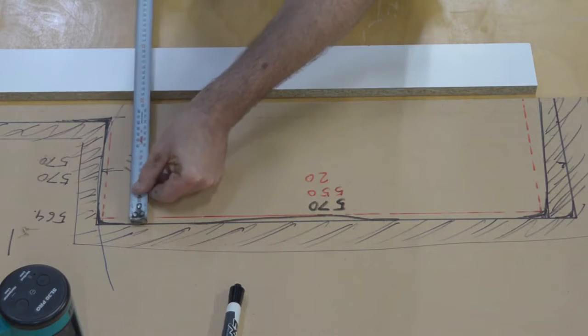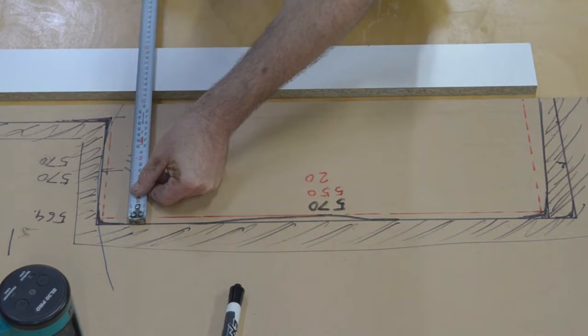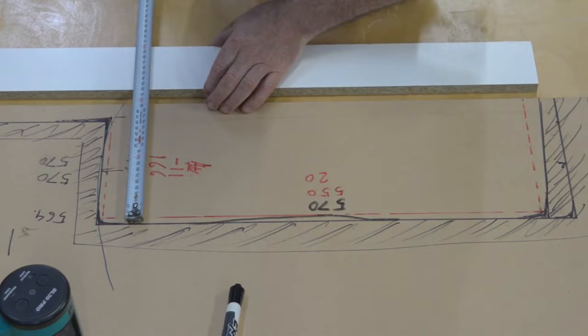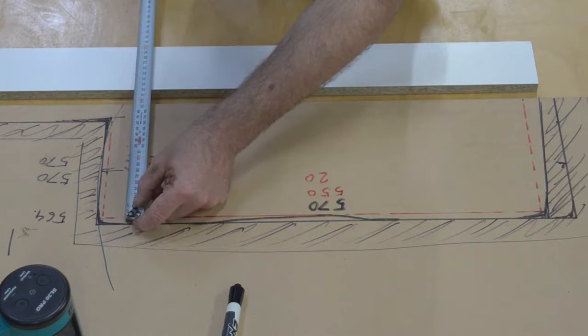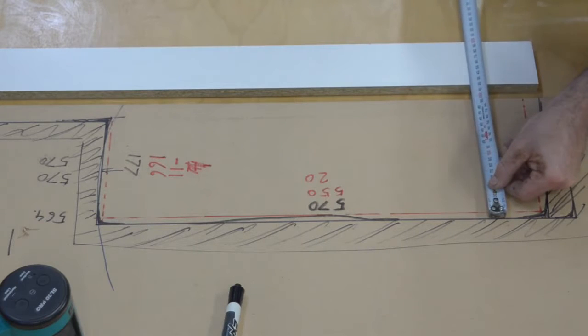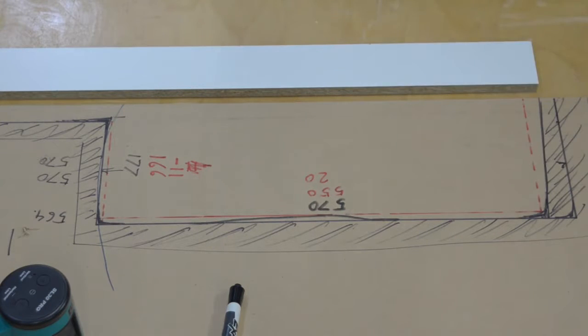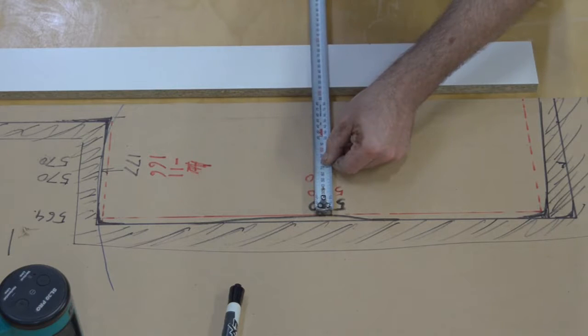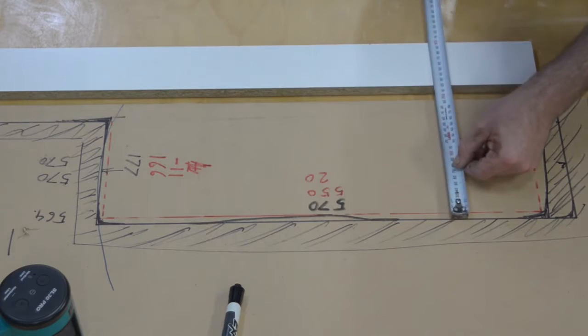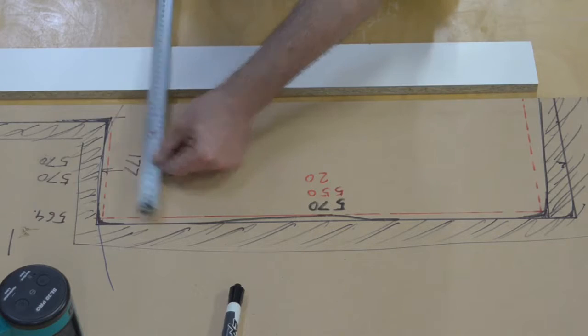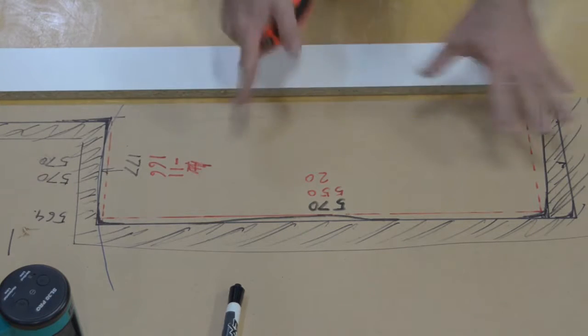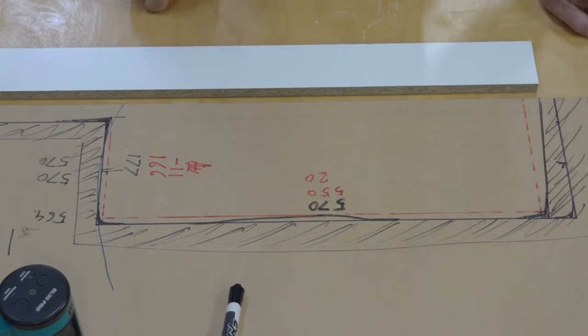Okay, this is our wall. This particular dimension here to my plank is, say, 200 and I'll make it 220, so I've got a consistent space. So I'll make this side 220, and that side also is now 220. So I could go along and look for any bumps. So that's 210. So that's telling me already, comparing to my plank, that we've got a 10 millimetre variation. And so my temptation is to throw another 5 millimetres in there just as a tolerance, because there'll be other variations.